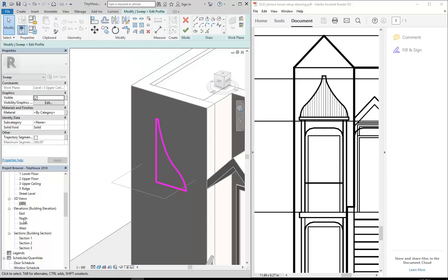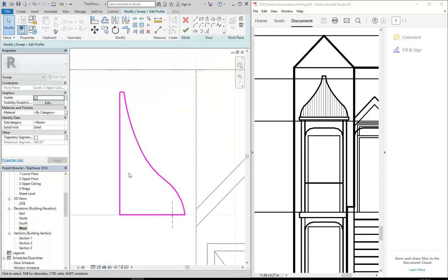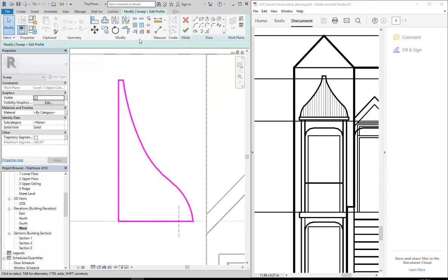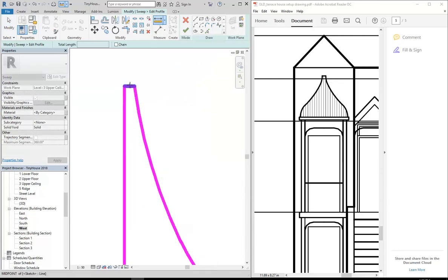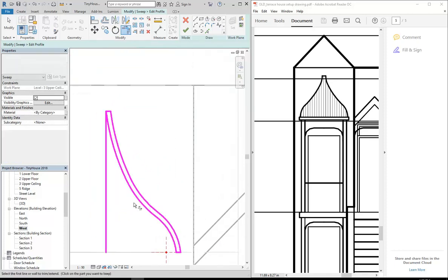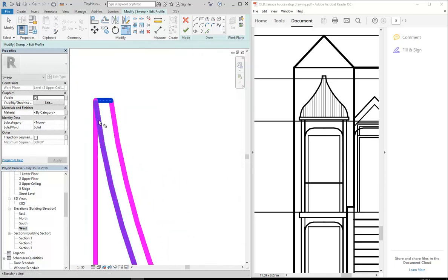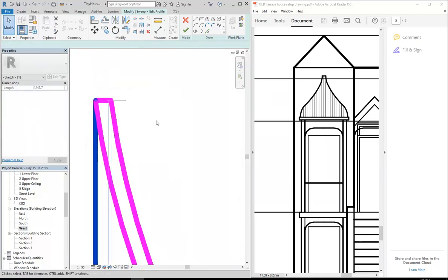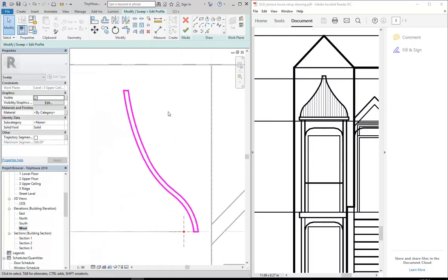And then in my west elevation, just to make it easier, I might just measure this distance. I don't know what that was, but 40 mil, that sounds good. Okay, so I'm going to use the offset tool there and make the offset distance 40. And then simply just pick all of these lines, or these arcs, really, and then use trim to corner to join that together to make it again into a closed shape. Just delete that line on the left. So that's better still.